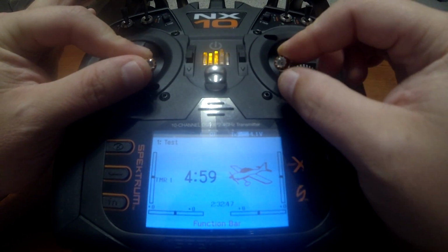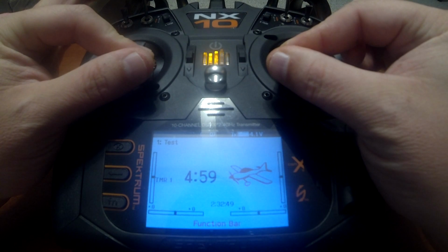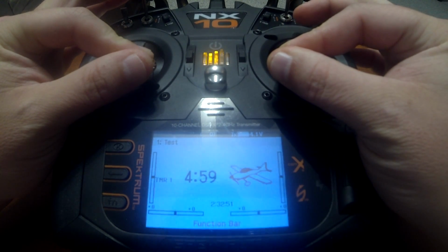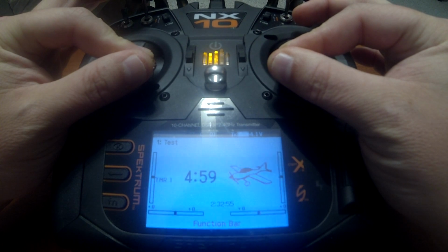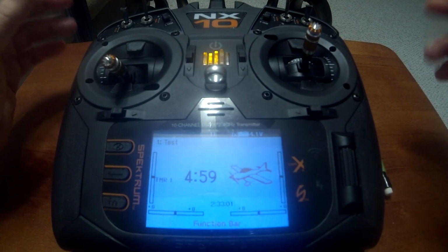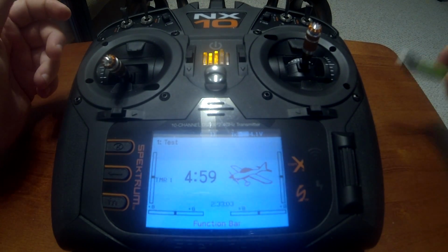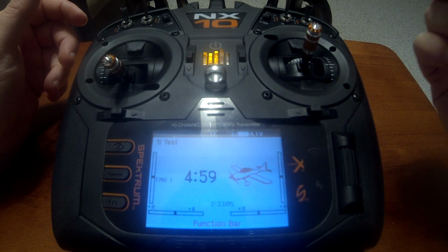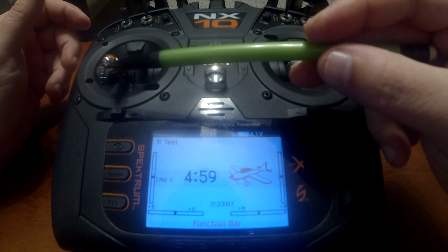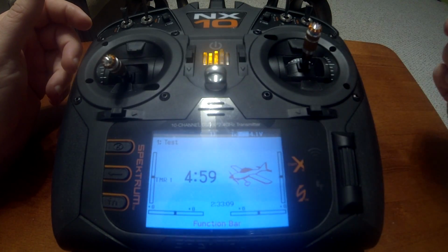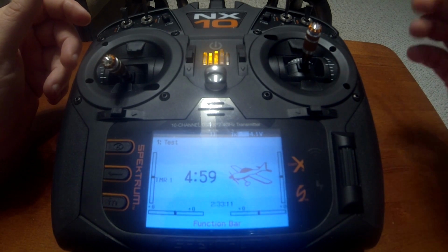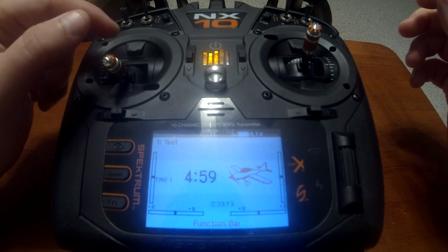Once you've toggled it 5 times while holding the sticks down and in, the airplane will wag. Keep holding it until you hear the servos kind of bind up, and then they'll kind of relax. That's when you can let go of the sticks and the process is completed. You need to have your throttle over 25% and back down for this to activate as well. So the way you can check it is go over 25%.